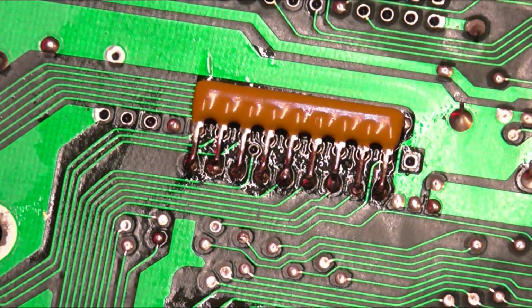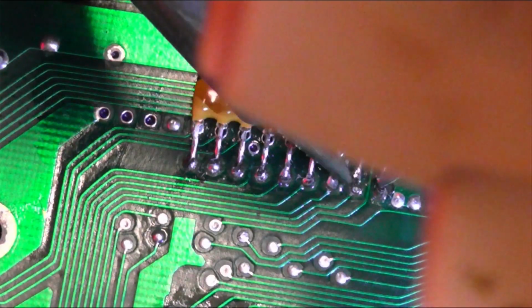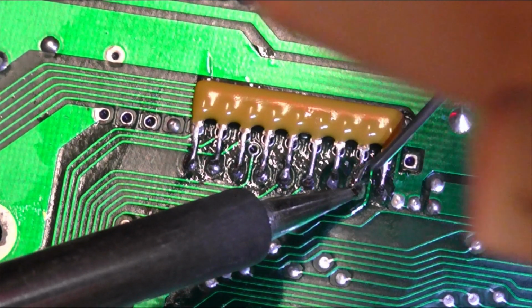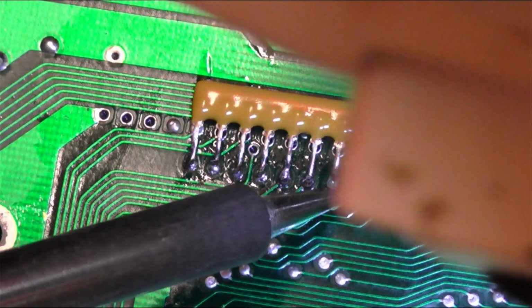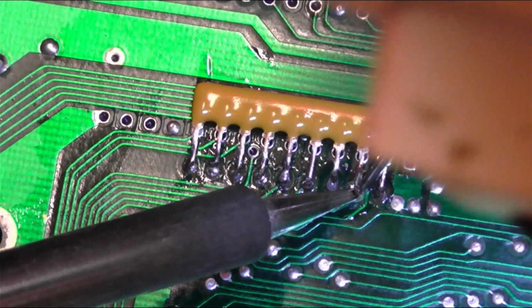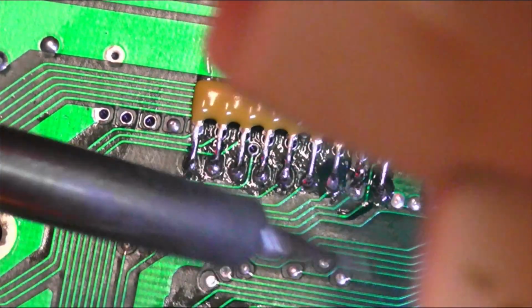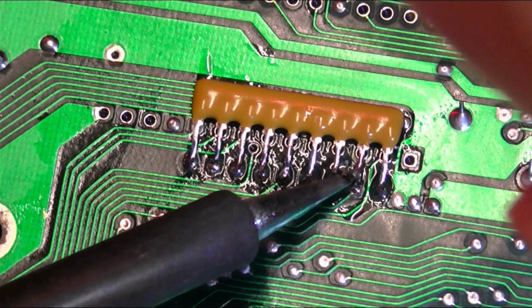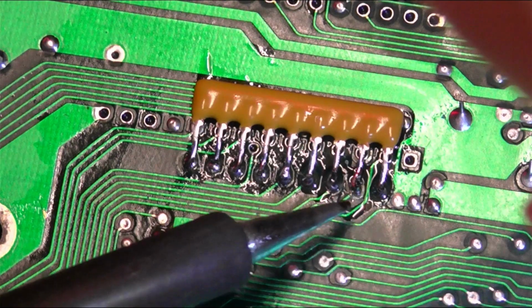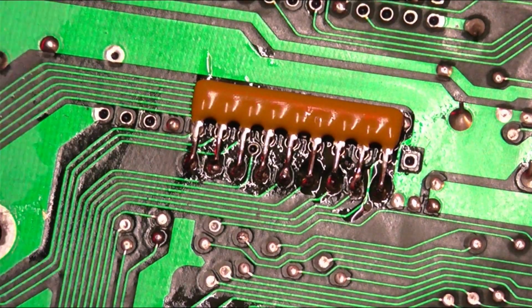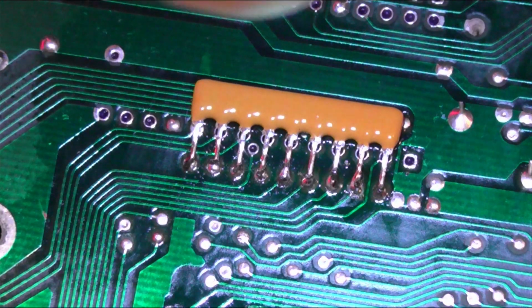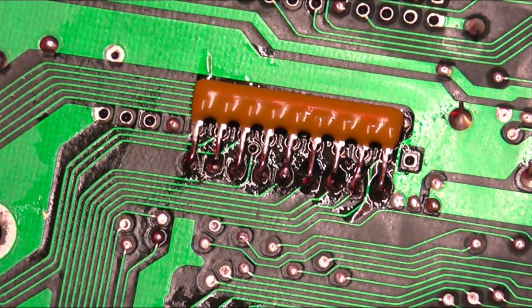Nope, it's floating. Okay, let's get back in there again. Don't seem to be able to heat the pin well enough. Maybe that... got it there. No, it certainly doesn't seem to be flowing. Okay, that's ugly, but I'm pretty sure that's now made a connection. Yeah, again, as soon as I wipe off the flux, it doesn't flow.